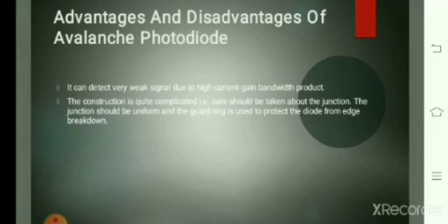Disadvantages of avalanche photodiodes: a much higher operating voltage may be required. The avalanche photodiode produces a much higher level of noise than a PN diode. The avalanche process means that the output is not linear.